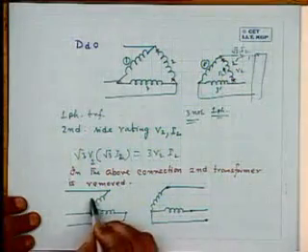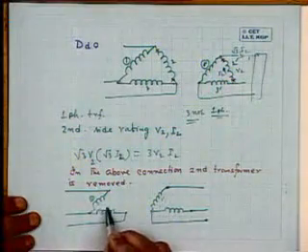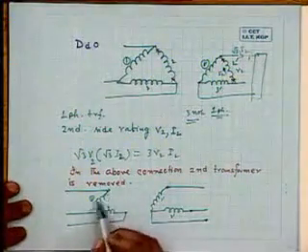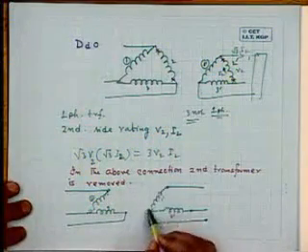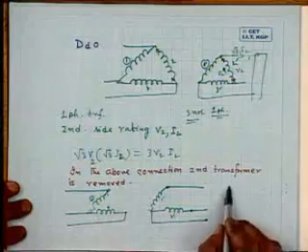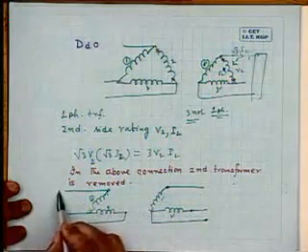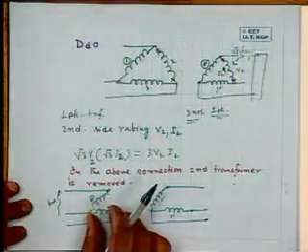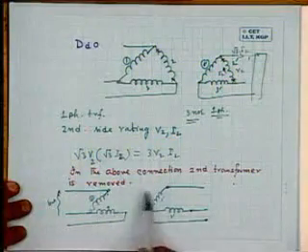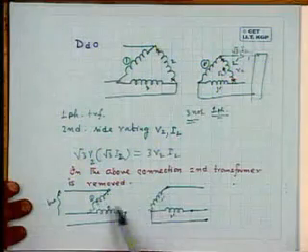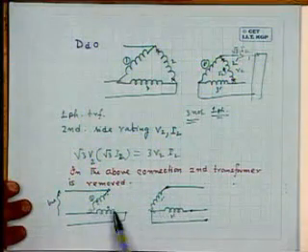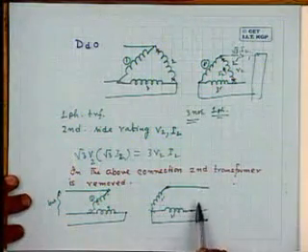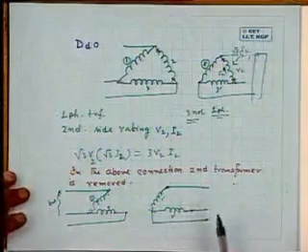You give 3-phase balanced supply to these 3 points. So transformer 1 is present, 1 dashed is present, 2 is present, 3 is present, 3 dashed is present. Now, what is the voltage impressed? Sinusoidal voltage. So, induced voltage here will also be sinusoidal. From the input voltage triangle, input voltage is balanced. Therefore, this voltage has got 120 degree difference. So the induced voltage here will be in phase with 1 and here induced voltage will be in phase with 3. Tell me whether you will get a balanced three-phase output voltage on the secondary side?